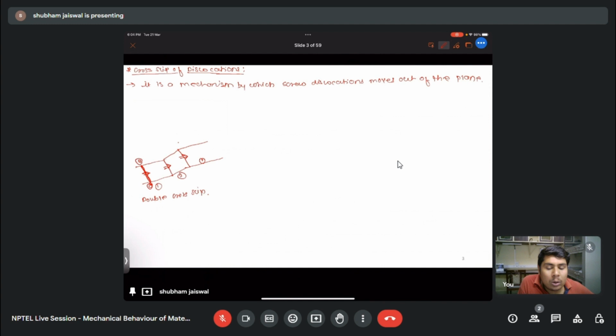In the case of a screw dislocation, the Burgers vector and line vector are parallel or anti-parallel to each other. So there is no unique plane defined by the cross product of the Burgers vector and line vector. It means there are theoretically an infinite number of planes available for a screw dislocation to cross slip. But there are some constraints defined by the slip system, which restrict the number of planes for cross slip to occur. There is always more than one plane available for a screw dislocation to cross slip.